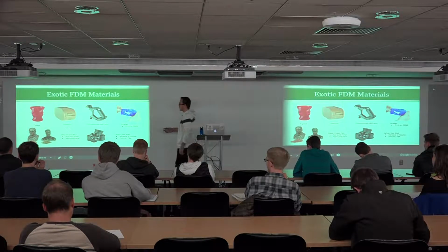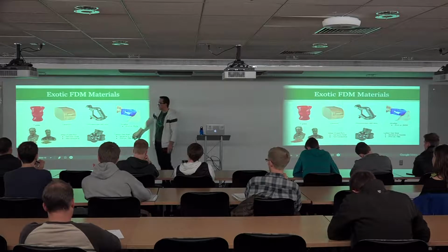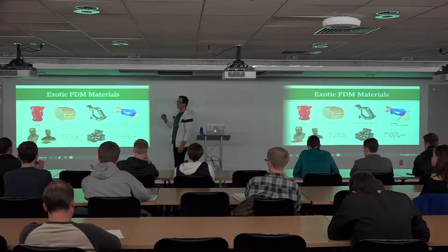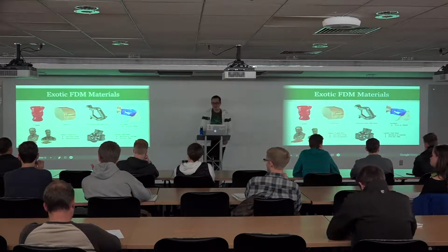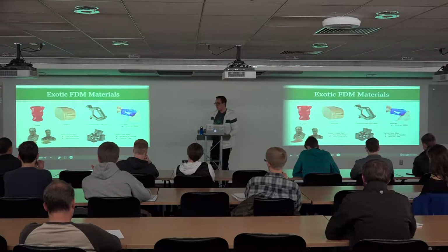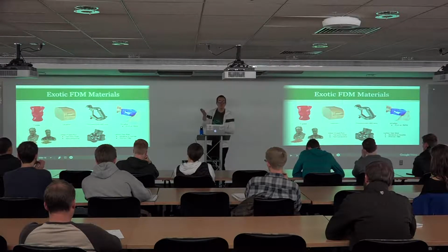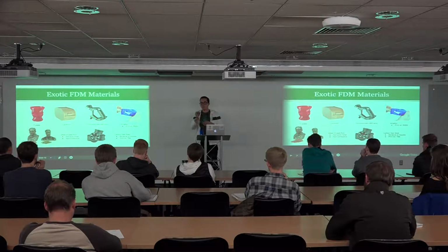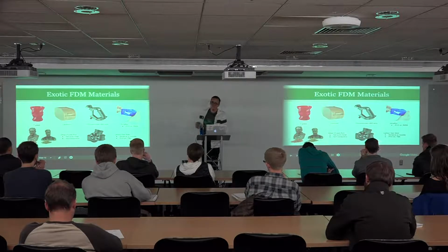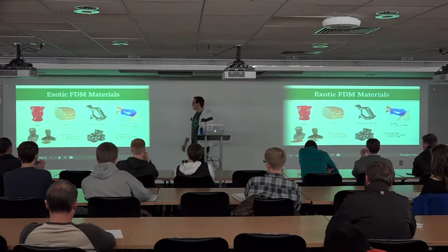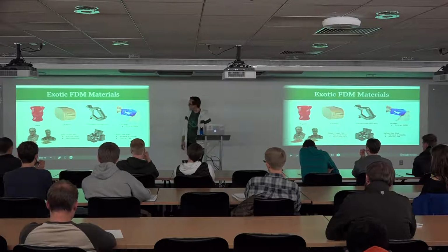Yeah, you can get just chopped carbon fiber in like nylon. We printed with some of the Nylon X from Matter Hackers, and it was pretty cool. But you print with a whole spool of it through a brass nozzle, and you know, carbon hardness versus brass hardness, the brass loses and your nozzle slowly gets really, really big. It's literally just wearing it out into a larger nozzle size. So that's why we need special hardened nozzles to print it continuously.